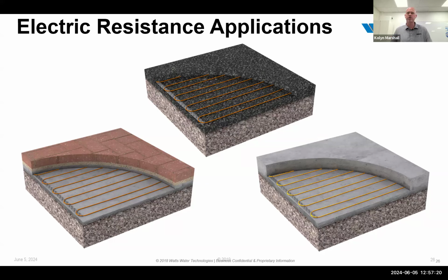It's not unusual to see a fluid temp of about 160 plus degrees for asphalt. And that's fine. It's not an issue. My boiler's running at 180. I have the capacity. Here's where asphalt systems tend to lose their edge.